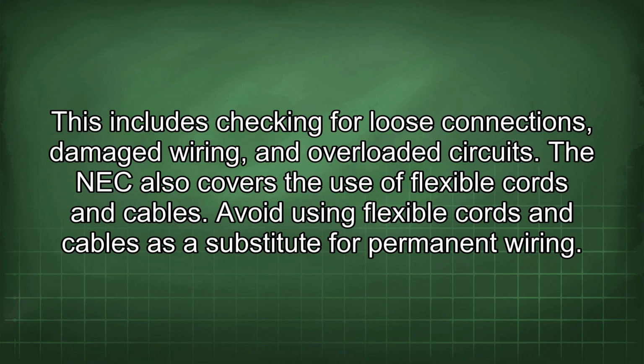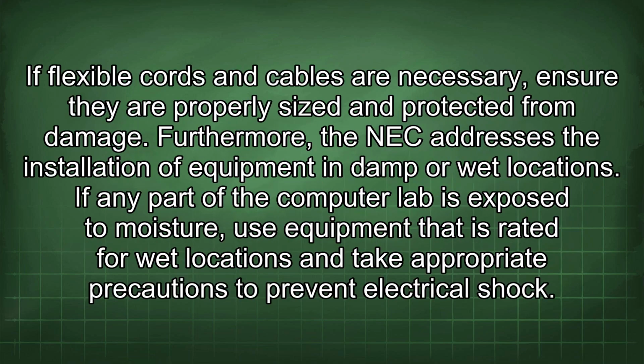The NEC also covers the use of flexible cords and cables. Avoid using flexible cords and cables as a substitute for permanent wiring. If flexible cords and cables are necessary, ensure they are properly sized and protected from damage.